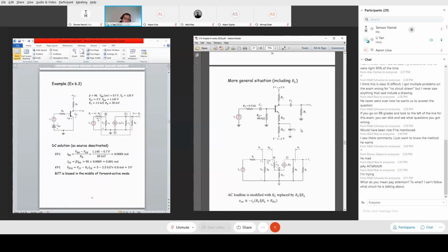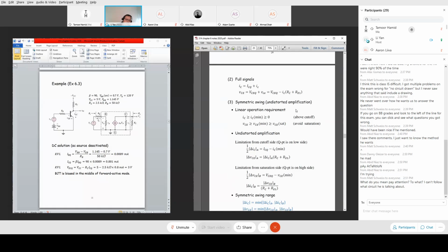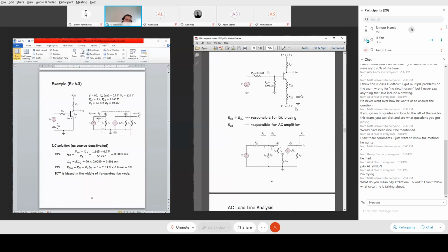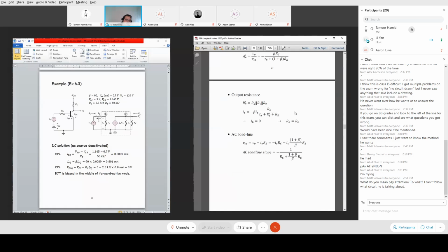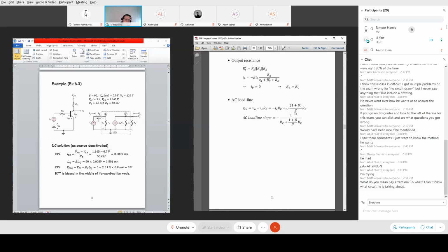So that last part is just saying for this particular circuit, you have to include the VCEQ. But for some other circuit, depending on where the final output is, you have to decide whether the DC part is filtered out or not.